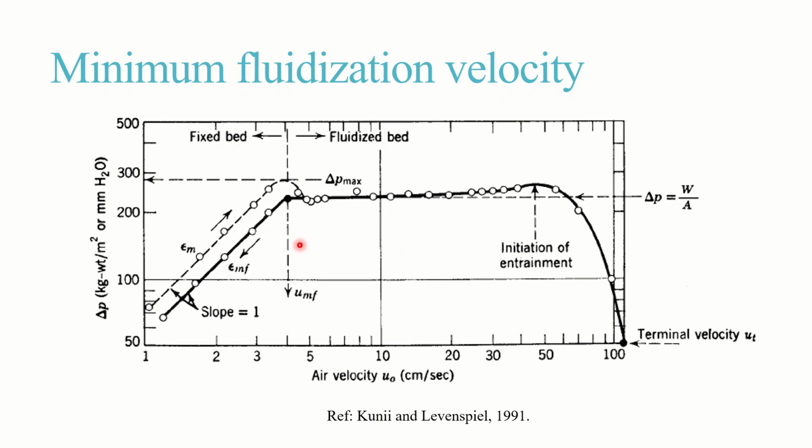Till a certain point, the drag force would be very low compared to the gravitational pull, because of which the particles remain in the packed bed or fixed bed condition. So the pressure drop would keep on increasing till the point of fixed bed.